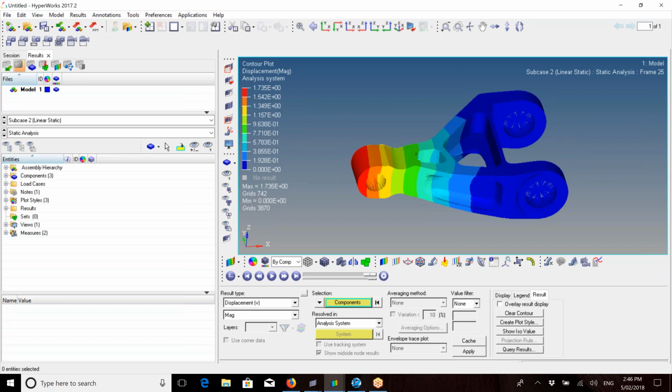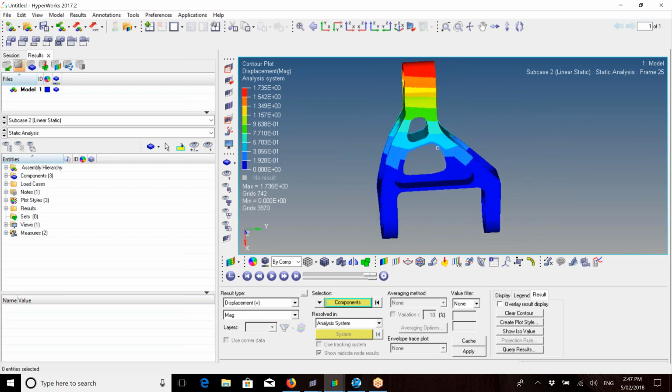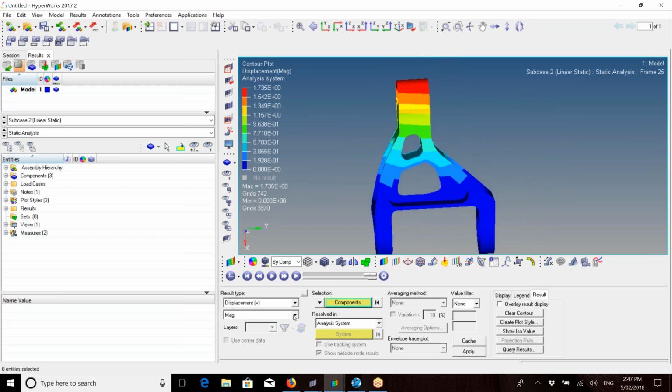As expected, this is pushed up in regards to the bending, and it's also pushed in towards the constraints from the compression. So we shouldn't see any real displacement in the Y, but we can check that by changing the magnitude, and you can choose the axes that you want to go in. So let's just see what happens here in the Y without a force directly pushing it that way.